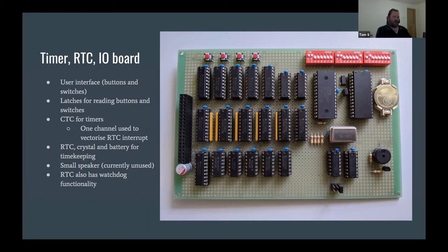But because you have one common anode and then all of your cathodes are broken out, there's no way to really limit the current with the resistor. Yeah, I'm thinking too, maybe with open collector drivers or something that would have actually worked. Yeah, well, this works potentially as well. With common cathode, maybe. There might have been a way to do that.